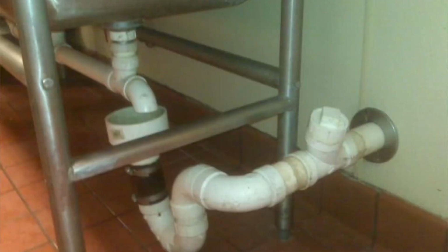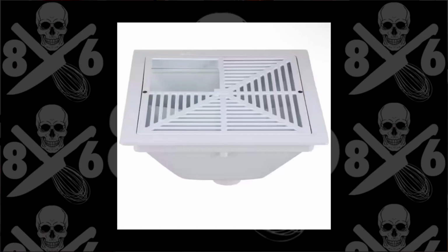You might notice that, or you might notice a pipe directly over some type of grate. That's because it is absolutely required. If that sink is directly connected into that, there is a chance of backflow. Maybe there's a flood and the sewage comes up, and now it comes up into the bottom of the sink because there's no air gap. Maybe the sink gets clogged later on down in the pipeline, and all of that old stuff starts making its way back up as you start to fill the sink up. That's why you need one of these things.